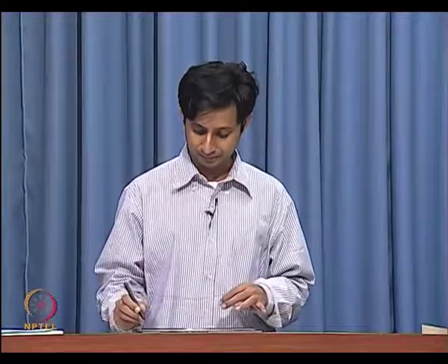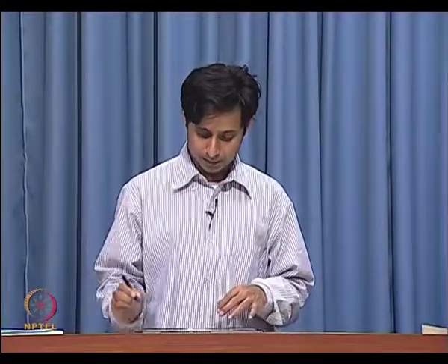How do I match the RF signal that is coming from the LNA to the input of the mixer? The input of the mixer is looking like a capacitor. So, there is not going to be any power transfer at all. So, I can't do matching at all. So, that is problem number 1, right. Problem number 2 is maybe the capacitance is going to be too much,